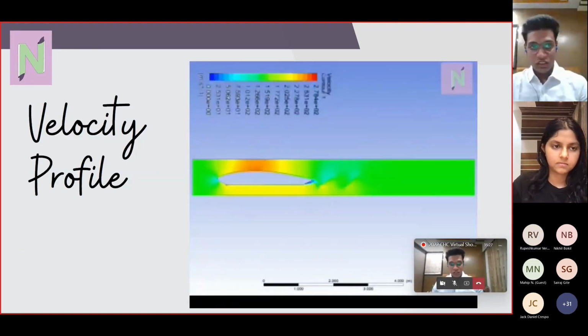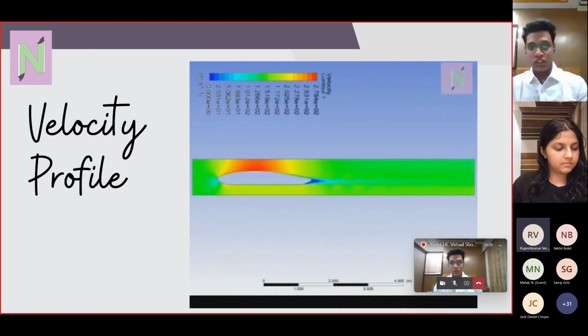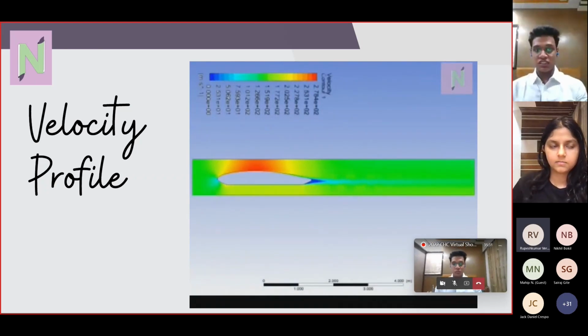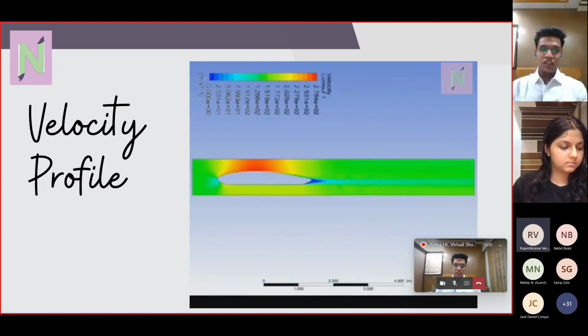At low Reynolds number, some vortex shedding at low speed during the transition and the acceleration of the pod can be observed. In fact, accelerating until the full speed will make the pod pass through all the Reynolds numbers. Therefore, a transient analysis was also done, and the velocity profile video is on the screen.